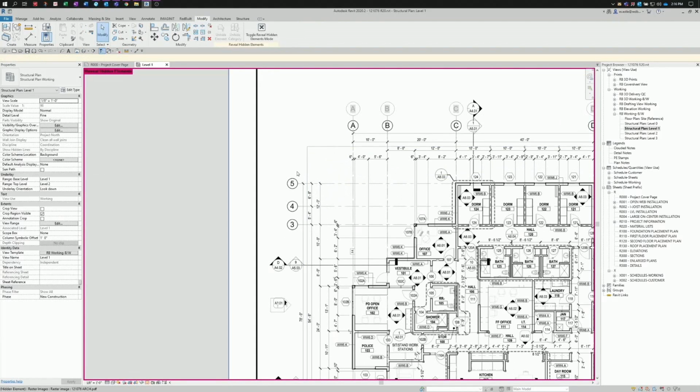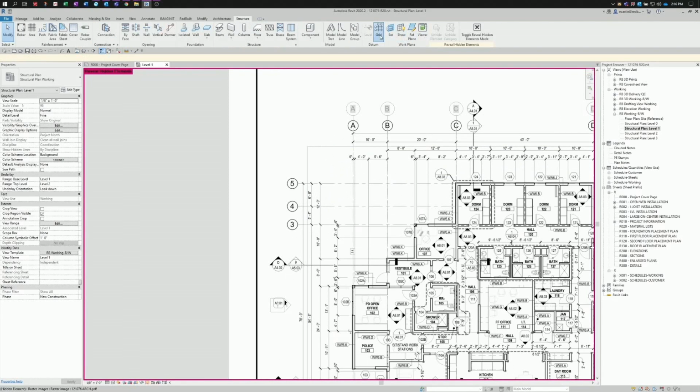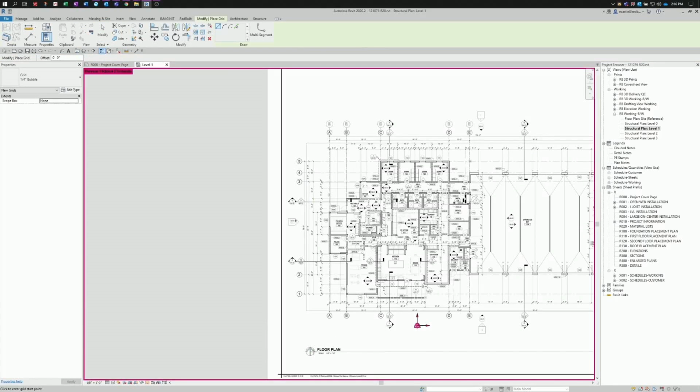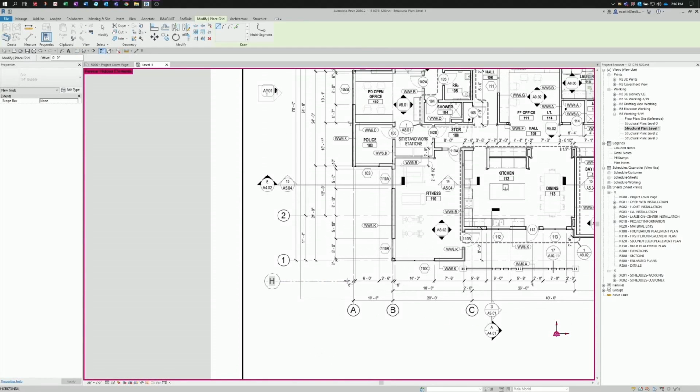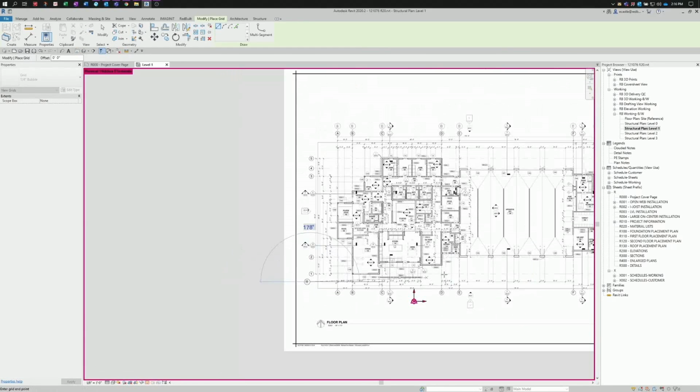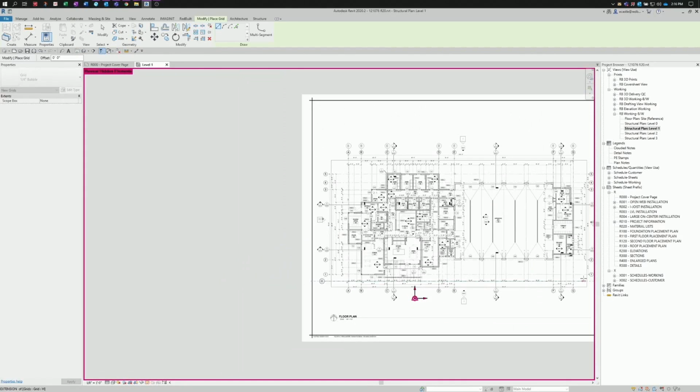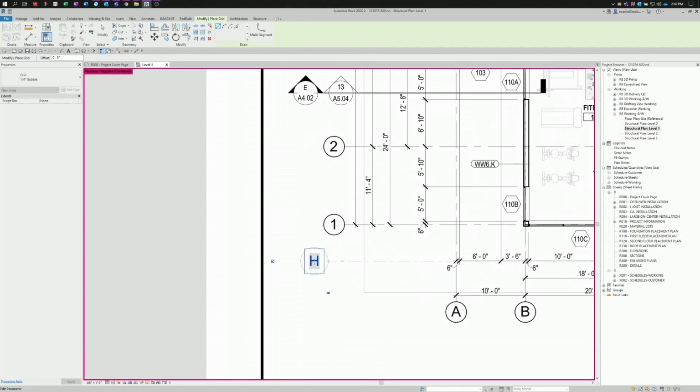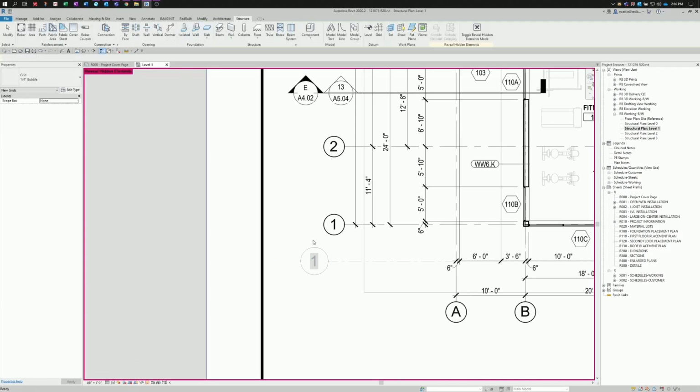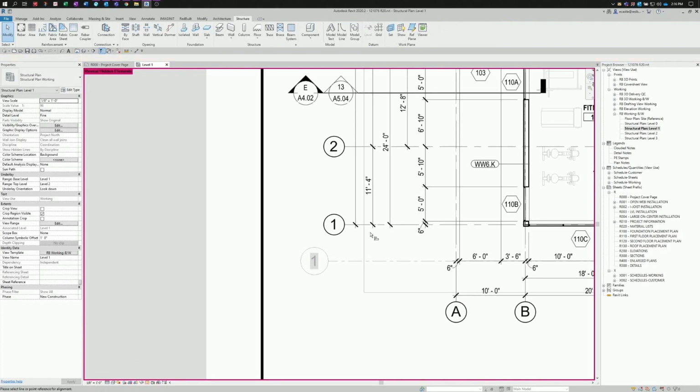And this I'll cancel and do the horizontal. We want to start the process again. Start at grid 1. Draw our first grid. Change the text to 1. Cancel out and align.